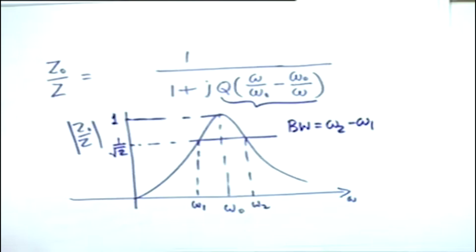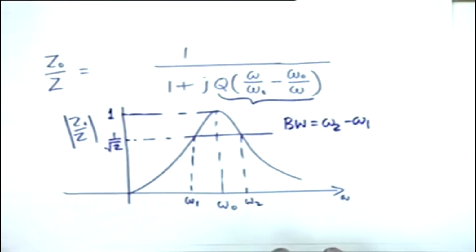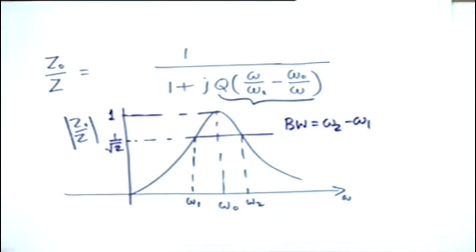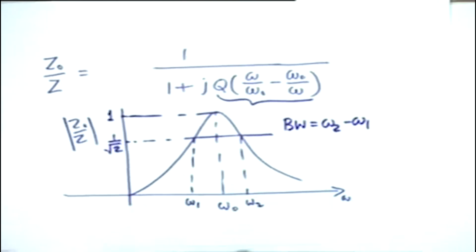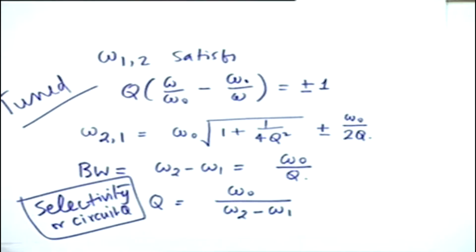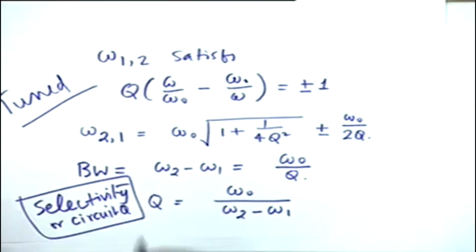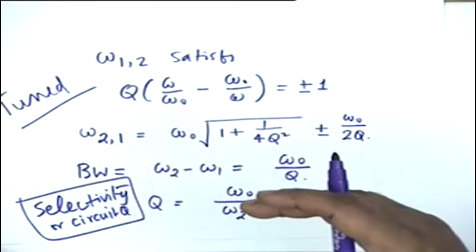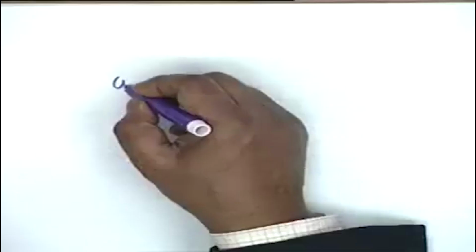The basic condition for resonance is that the current and voltage are in phase. That's right. The phase difference between current and voltage is 0. This is defined as the condition for resonance. This is why the voltage maximum across an inductor is not necessarily at the resonance frequency. That is not a condition of resonance. The voltage maximum across a capacitor occurs at a slightly different, slightly lower frequency, and that is not the condition of resonance.